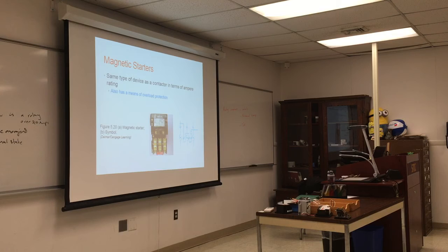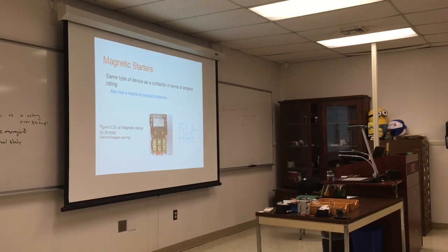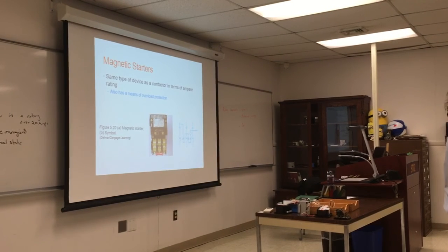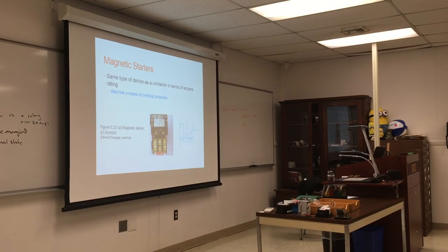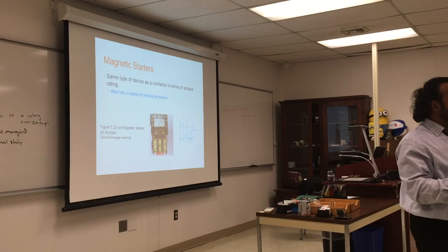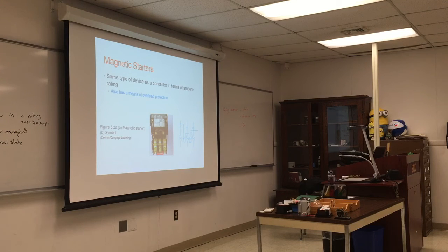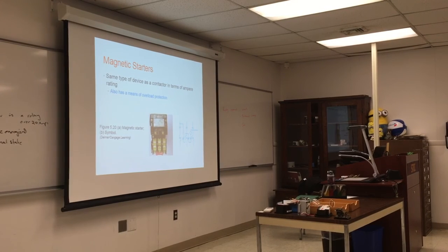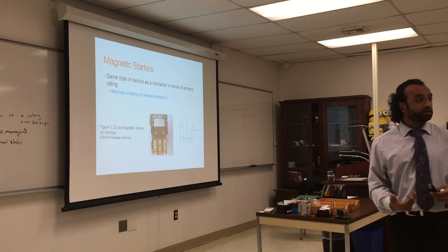When do you think it will trip? When you require too much power. Why will it trip? Because you exceeded the amperage. What is a situation where we will draw too much power? Startup, yeah, but in what situation? Exactly, heavy load. The motor is stuck, and the motor is huge, trying to turn a compressor, so it's going to keep drawing power until it trips. If it doesn't trip, what will happen? It will overheat and burn out. So it's a way to protect the motor or the compressor.